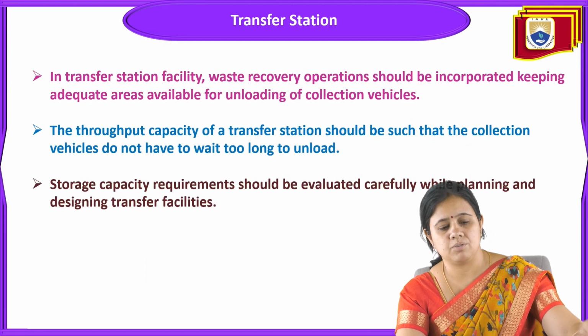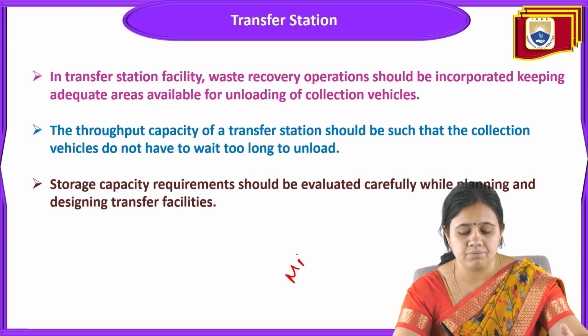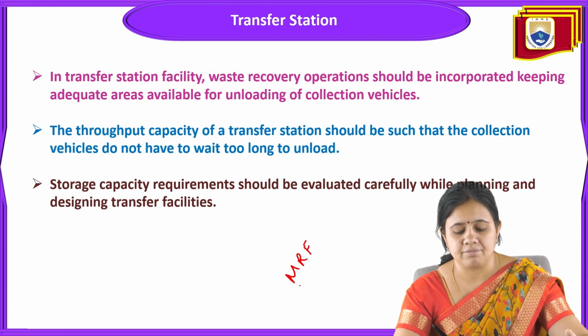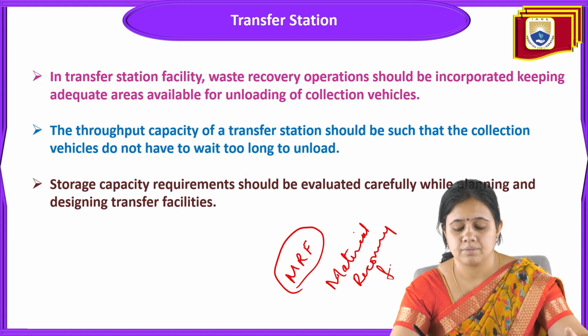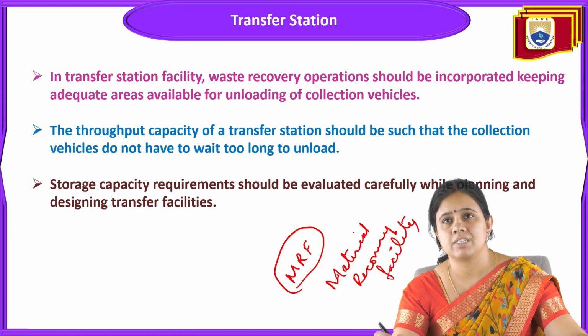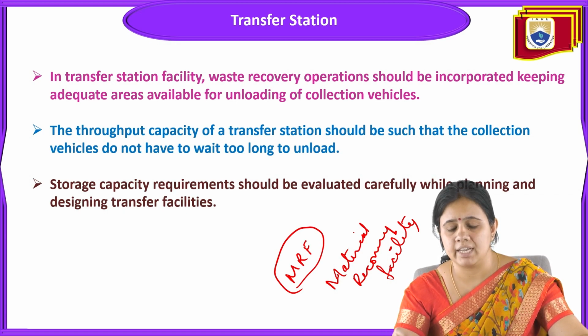First of all, the transfer station. Transfer station means a material recovery facility site, MRF, material recovery facility center. In a transfer station facility, waste recovery operations should be incorporated, keeping adequate area available for unloading of collection vehicles.